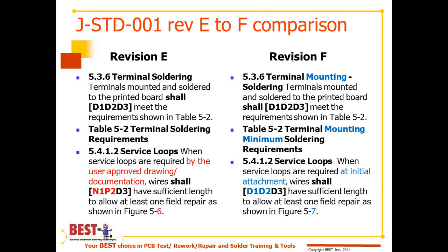Under 5.3.6, for terminal mounting, they've just added the word mounting in there for soldering. And the table, they've added the mounting requirement to the table. So rather than just terminal soldering requirements, it says terminal mounting minimum solder requirements.